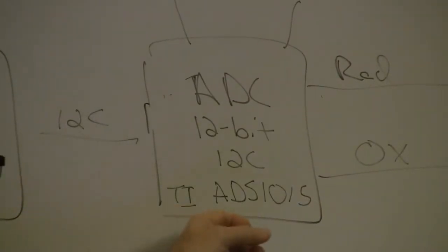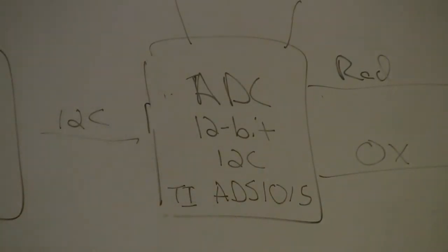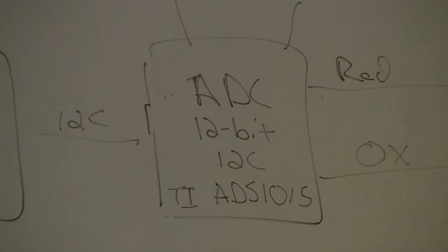And then I use an analog to digital converter, a 4-channel A to D converter that would take the output of the sensor, but then I thought, well, heck, just put another analog thing on there, which has been really helpful in debugging, because I can use the ADC to measure voltages around the board, but also measure the battery voltage.